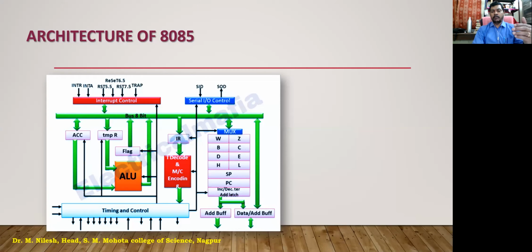When you perform some programs, you'll find the first instruction is, say, load HL pair, which implies that the HL pair is to be loaded with the memory location first. This is the address of the memory location where the data is stored.